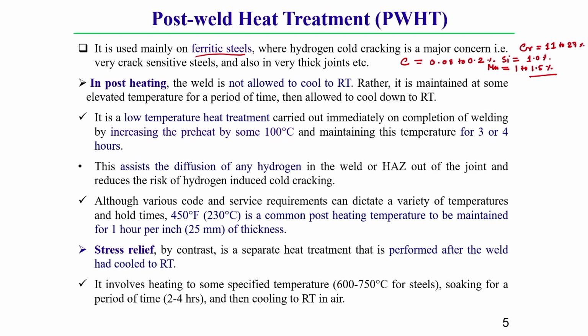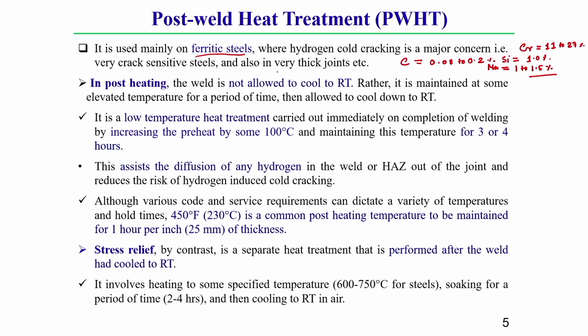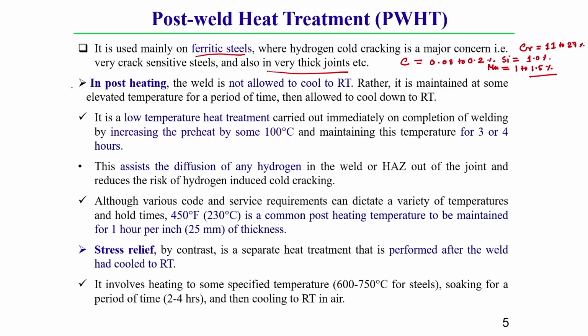And what happens, it is also more critical once the thickness of this ferritic steel is a little bit higher. That is why I have written, hydrogen induced cold cracking is also more sensitive if the thickness of the plate is higher. Okay. Now, first of all I will discuss briefly what post heating is and what stress relieving is.